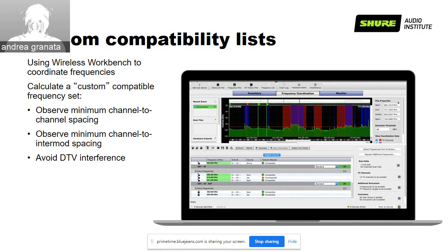Oh, I see that in the chat, Ranjan is kind of correcting me. LED screens have highest emission to the sides, front and back, less at 45 degrees. Yes, partly, but between the front and back, there is a significant difference. Then again, it depends very much on the LEDs. Transparent LEDs are more omnidirectional. The bigger tiles are emitting much more RF at the back.